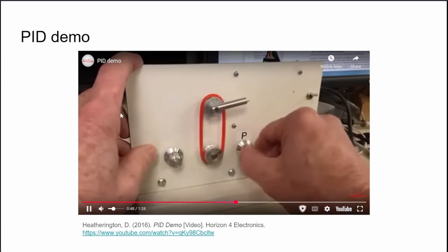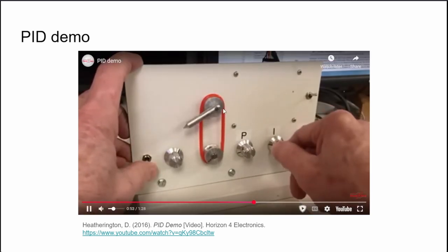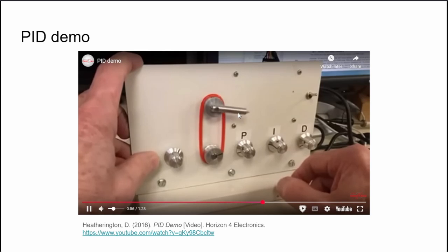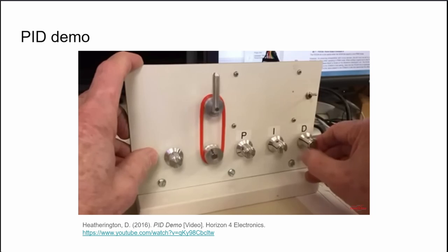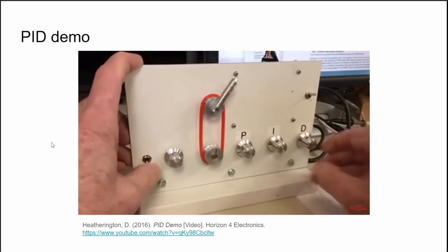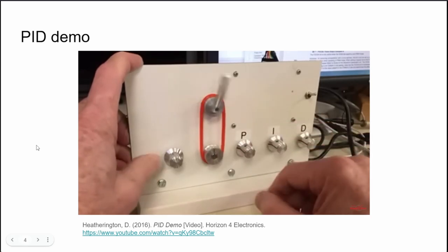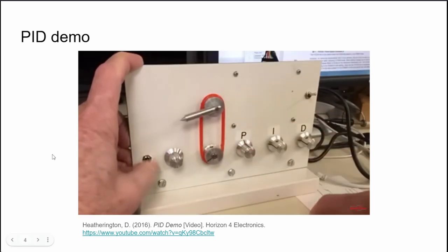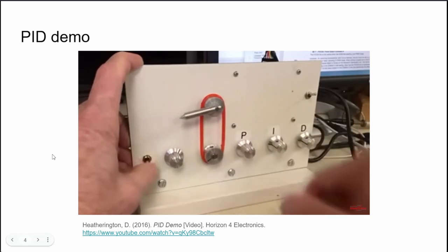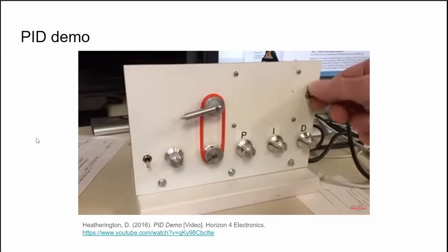So you can see when the integral tuning is increased later, it'll give a boost to make it to the target position. So you can see it doesn't quite make it, and now with the integral it'll go all the way. At the end, you'll have a pretty good PID tuning where it reaches the target in adequate time with minimal overshoot. So you can see when P is increased, it'll move faster. But then eventually it'll overshoot and it'll wiggle.